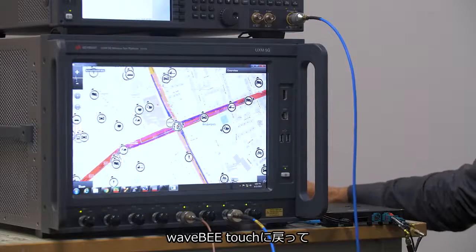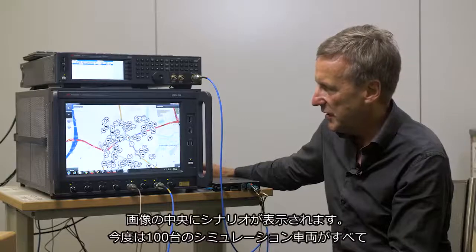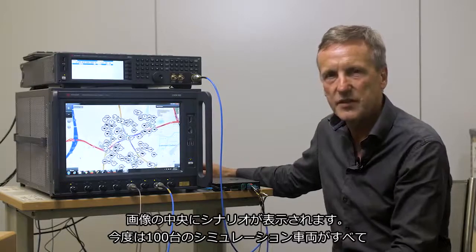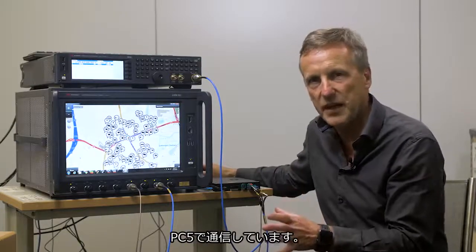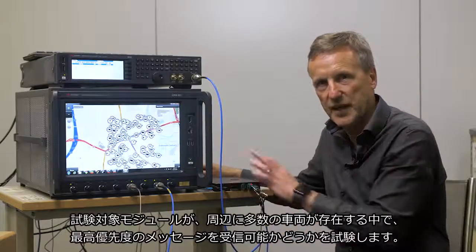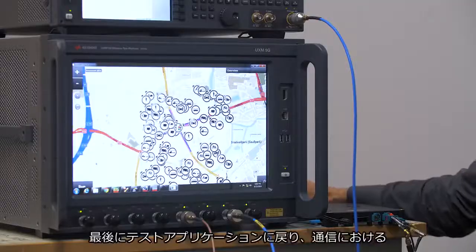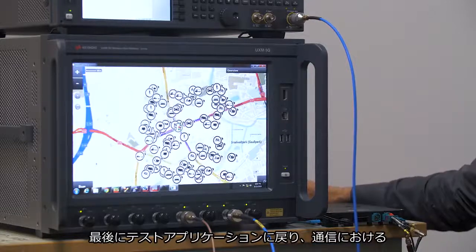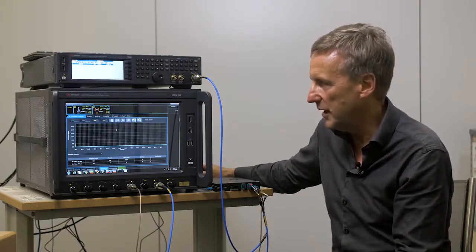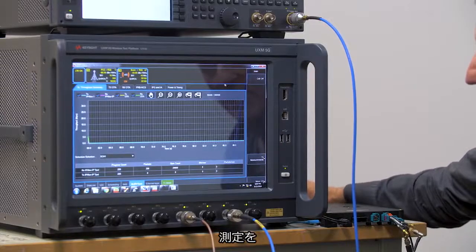If I go back to my WaveB Touch and I expand out, we can see here's the scenario in the center of our image, but we have 100 simulated vehicles all transmitting over the PC5 link. So the test would be, does my module under test still receive the highest priority messages in the presence of all these other vehicles? Finally, let me go back to my test application, and I'm going to look at the throughput from our transmissions. If I go local here, I'm going to start the measurement.